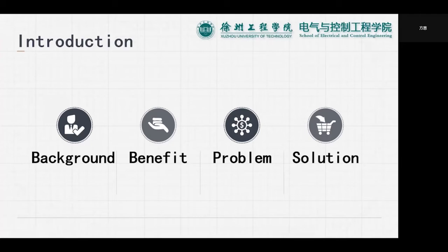The wide bandgap semiconductor materials have incomparable advantages over silicon materials. The power devices made by wide bandgap materials can meet particular environmental requirements and meet the development needs of power electronic devices better, such as high temperature, high voltage, and high power density. The superior electrical and thermal properties of silicon carbide power electronic devices compared with silicon devices lead to high efficiency and low volume in power converter designs.